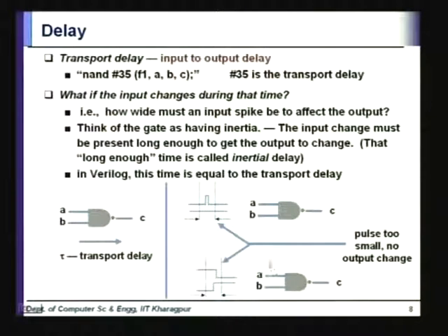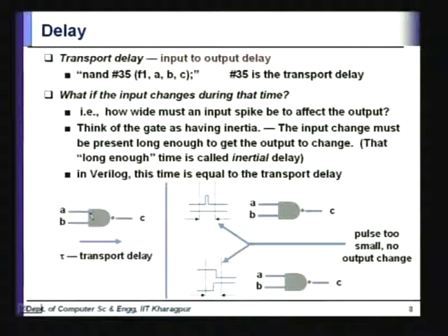Now this is basically the wire delay propagation. What is the reason for this? This delay is the delay that the gate itself takes. How does a gate change its state? The input that is fed here is fed into the gate of some transistor, in CMOS for example. There is a capacitance between that gate and the ground. So when this B rises, for example, that capacitance gets charged. So there is a charging delay for that. That is the delay of the gate.